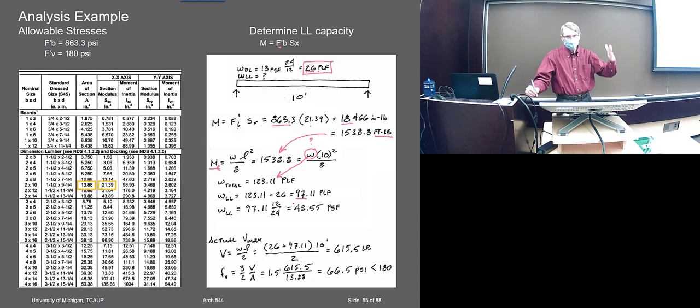But then it has a 24-inch spacing. This was based on a 24-inch spacing of the floor joists. So that comes out in terms of PSF on the floor, cuts it down to 48. It'd be half of that, right? 48. So, okay, easily would make your bedroom load, I guess.